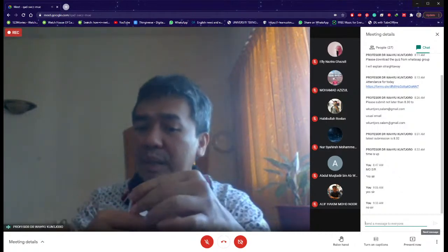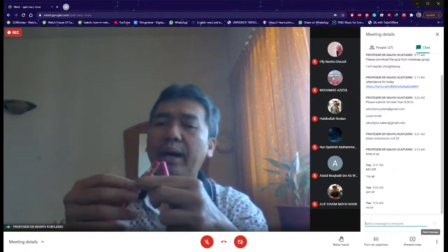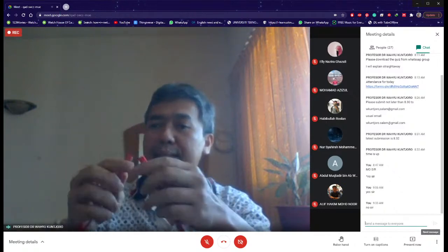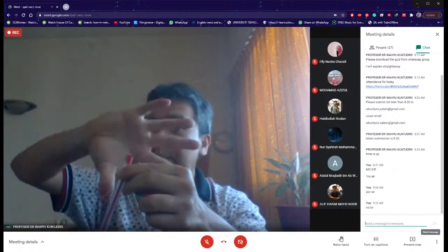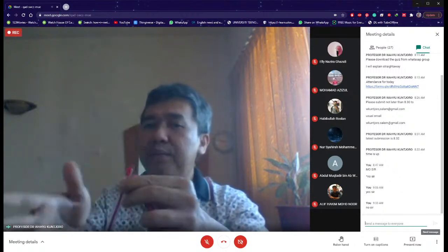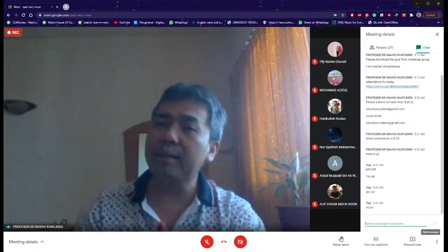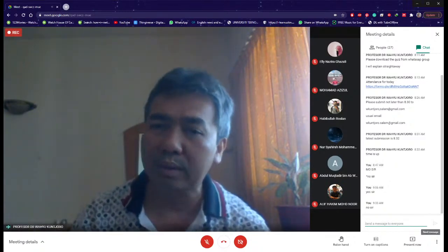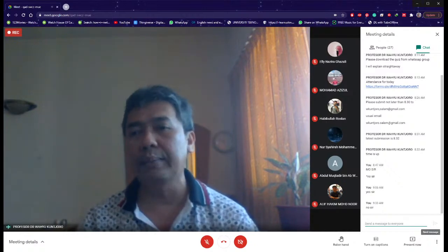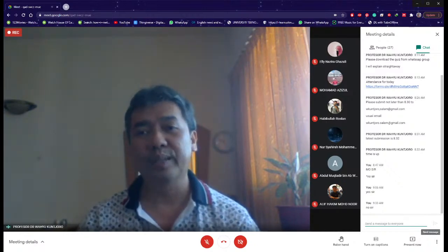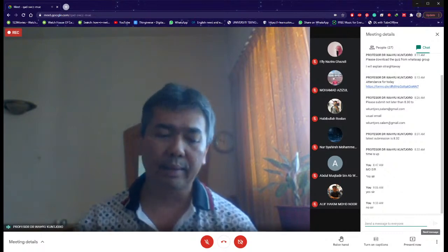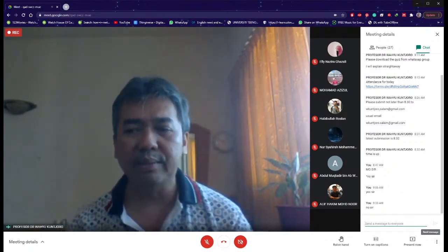Why it is not truss? Because if you have this as welding, then potentially you will have moment at any point. If you have moment at any point, then you do not talk truss. You are talking frame. All right. So I hope that answers your question.